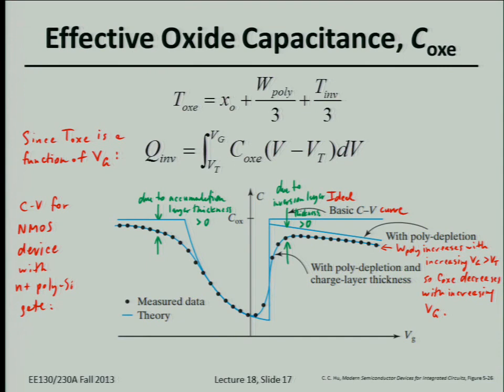And finally, in inversion, in this regime, the surface is inverted. We actually see this smaller gate capacitance, small signal capacitance compared to the ideal CV curve because of the gate depletion effect. So let's do black. This slope is due to the gate depletion effect.